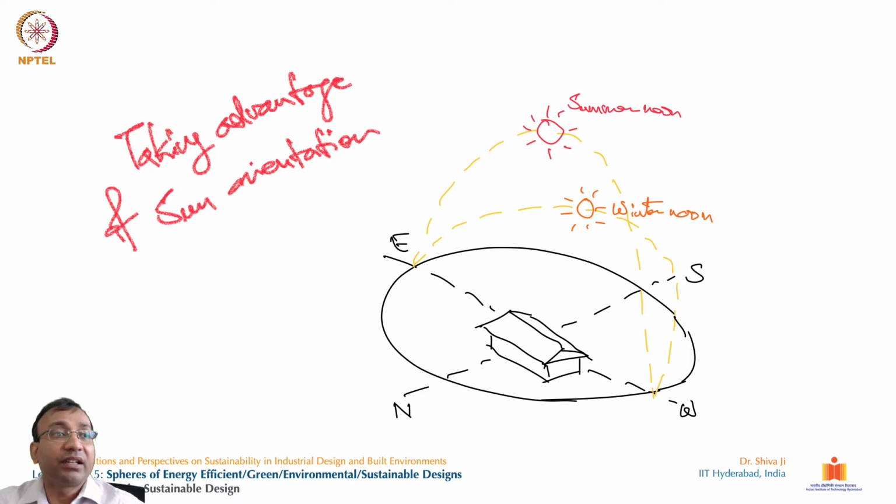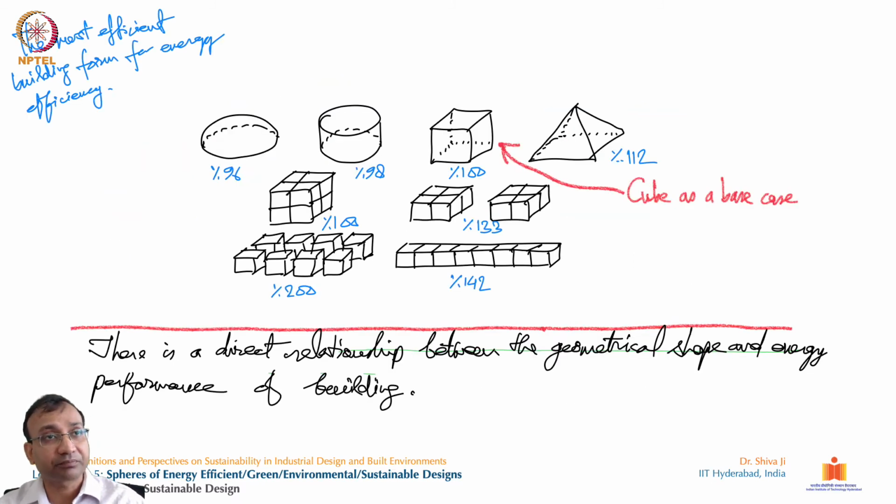So this is one sketch, you may have already seen it. With the location, the latitude and longitude, we can optimize the efficiency of the design by changing the orientation, the form, the overall volume, and the materials coming from that particular direction, depending on whether we need heating or cooling. Depending on that, we can choose facilitating materials, insulator materials, or conventional materials.